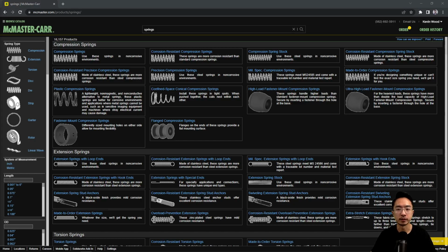All right, in this video, we're going to talk about springs. So, springs, you could typically categorize into three different types. You have compression, where you have to compress it to generate force that pushes back. You have extension, which you have to pull, and then the force is going inwards. And then you have torsion, which you have to rotate. So I would typically classify it into those three categories.